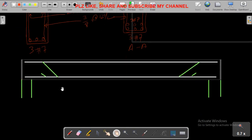And if we use the bent up bars arrangement, so in the case of the bent up bar arrangement, the detailing will be: this bar will be cut off at the same distance Ln by 20, and this bar should be bent up to the top, right? We already calculated this one.